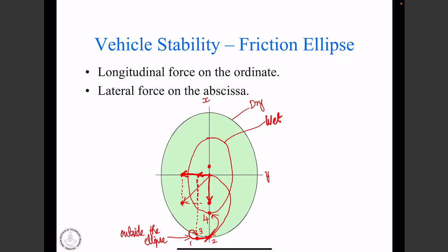All right. So that is why the ABS reduces the brake pressure and tries to maintain stability. But it is not very simple. If you look at the actual brake system, it won't smoothly go to 4. It will try to go to some other point here, by reducing the brake pressure too much. And then it will try to oscillate a little bit beyond 4, and it will keep on oscillating around this region. So we'll look at that shortly. All right. So that's how the anti-lock brake system works.